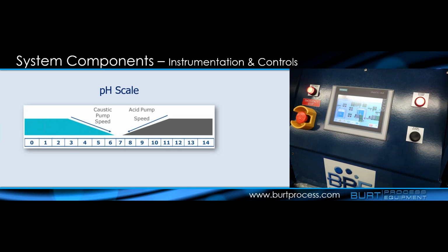As you start to get closer, 2 to 3, 10 to 11, you need to really scale down your chemical injection to match the pH curve, 10, 100, and then probably 1,000 to 1 turn down as you basically approach 7. That's how most pH control is done.